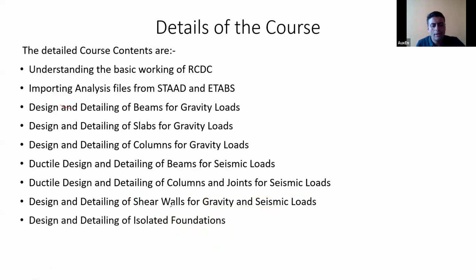After this, then we will discuss the foundations, different types of foundations, different options that you have for foundations. So you have got the different footing options like pad footing. You have got the option for step footing. You have got the option for slope footing. You have got the option for footing on raft. Footing on raft is not a very good option, but yeah, you have got those options. So we'll see how you can use RCDC for these isolated foundations also.